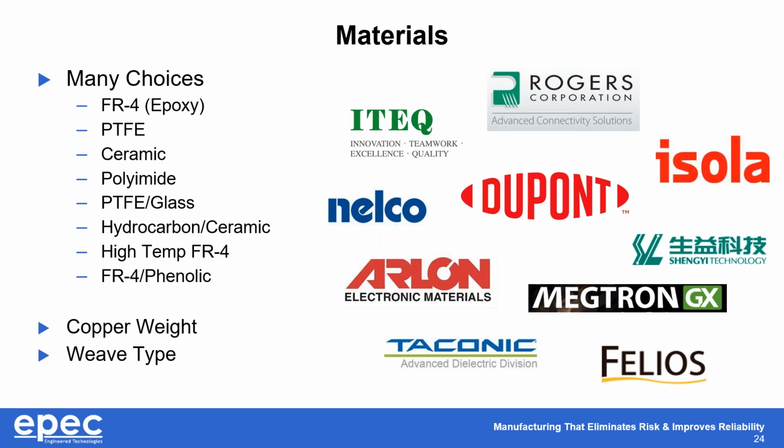I mean, as many of you know, trying to get DuPont laminate on the flex side right now can be 14 to 15 weeks. So being able to work with your fabricator ahead of time is really critical if you're trying to specify a certain product by vendor name rather than by anything else.